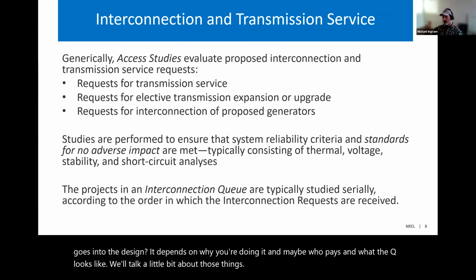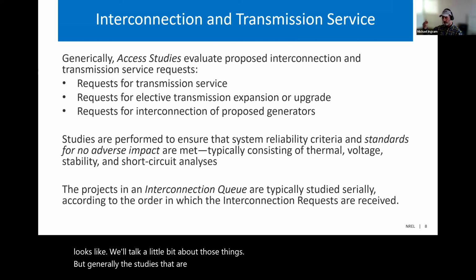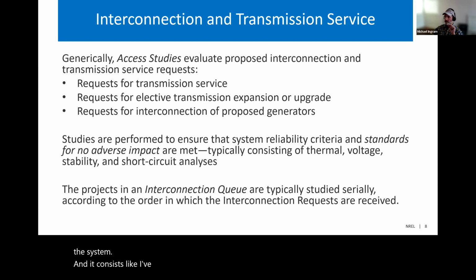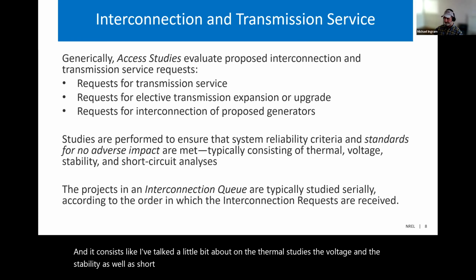But generally, the studies are performed to ensure that reliability is maintained, that there's no adverse impact of the change to the system on the remainder of the system. And it consists, like I've talked a little bit about, of the thermal studies, the voltage and the stability, as well as short circuit analysis.